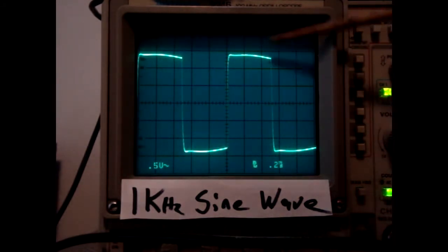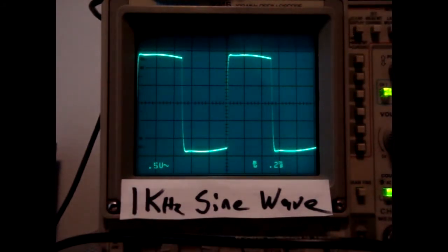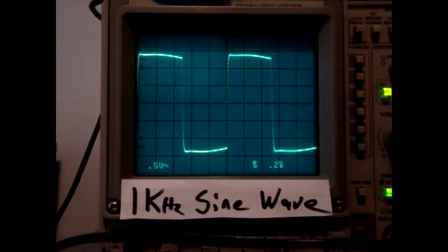And at the same time, the other end is the bass response. It'll start sagging if that's not right. So when I want to test out an amp, with the spectrum analyzer and everything, I'll usually set all the frequency controls so it most approximates this square wave.